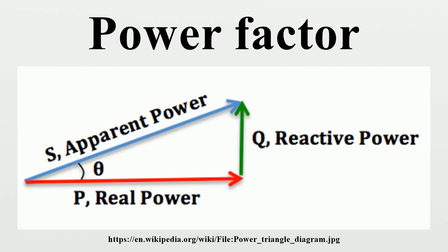Because AC distribution systems are essentially quasi-linear circuit systems subject to continuous daily variation, there is a continuous ebb and flow of non-productive power. Non-productive power increases the current in the line, potentially to the point of failure. Thus, a circuit with a low power factor will use higher currents to transfer a given quantity of real power than a circuit with a high power factor.